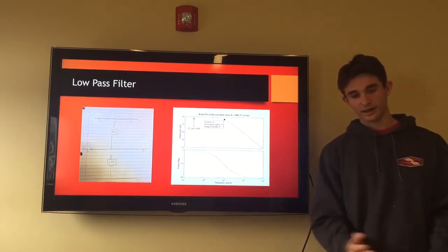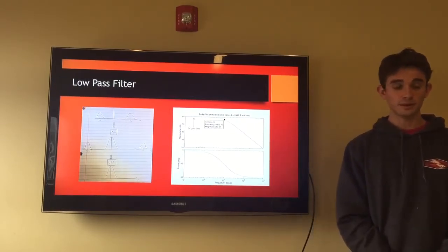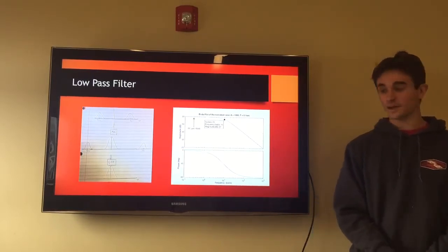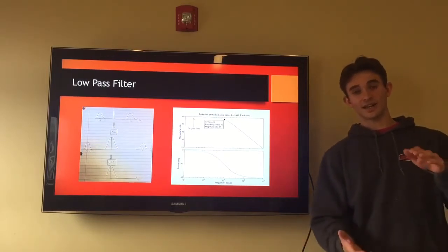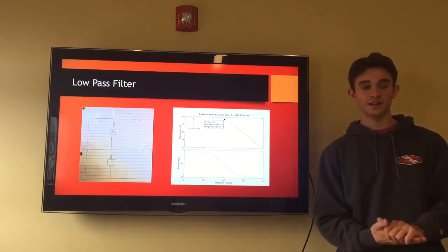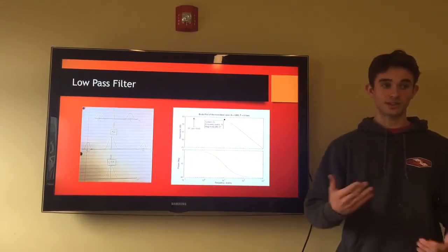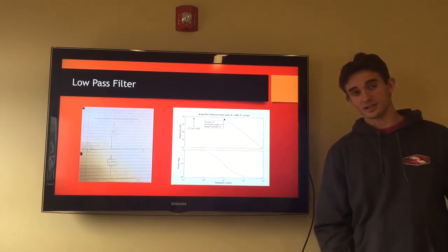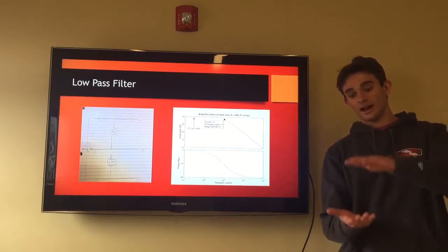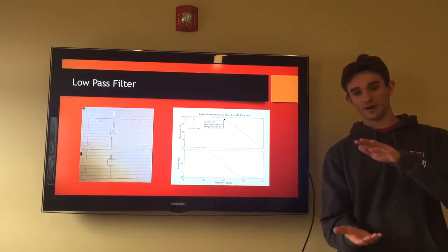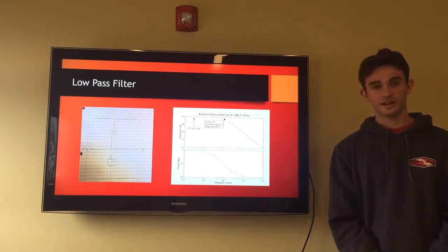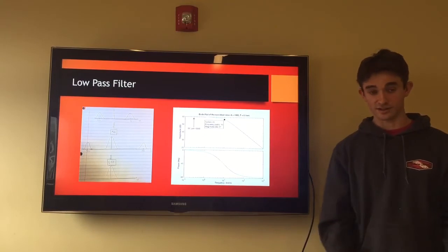An interesting thing in technology today is that we actually have programmable gain amplifiers. If I'm a really loud speaker, the receiving antenna recognizes it and lowers the gain, so I don't come out on the other end as a ridiculously loud person. But if I'm a really soft-spoken person, the gain on this programmable gain amplifier increases even more. So that's about it. That's how we receive signals in a typical cell phone.